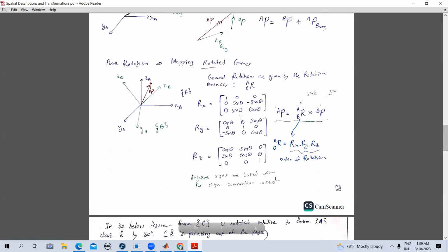So yeah, these are simply the rotation matrices. What this actually means is, assume that there's only a pure rotation in this case. Initially we have this frame, the frame A, and with respect to frame A there's a particular point, this red dot. What you do is rotate the frame. The point is fixed, but you rotate the frame. So it's vice versa, right? Imagine the frame is fixed and you rotate the point, and then you simply draw a coordinate frame identical to what was before to fit the point. Same thing, the only difference is what has been rotated and what's static.